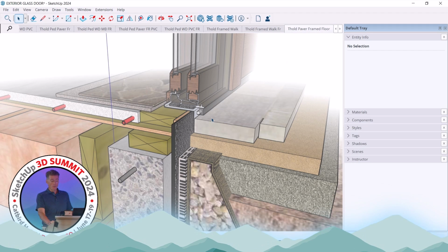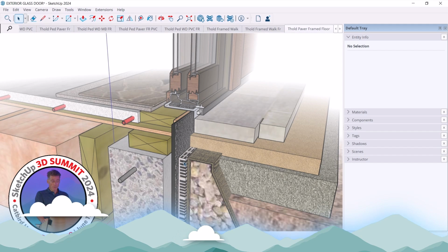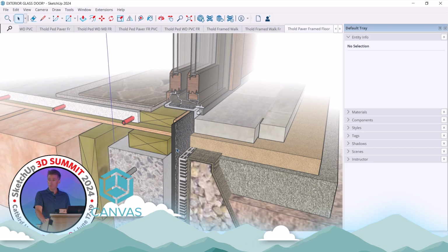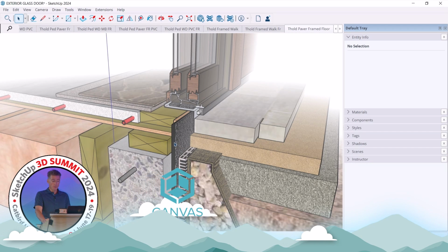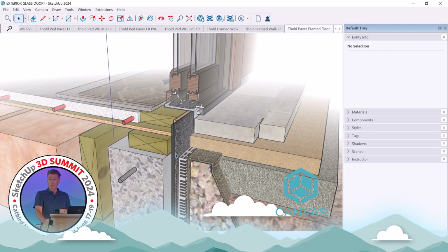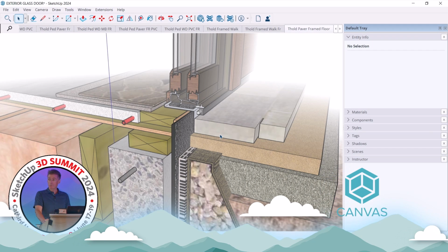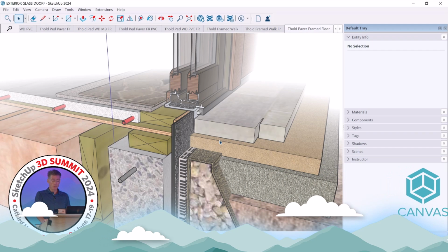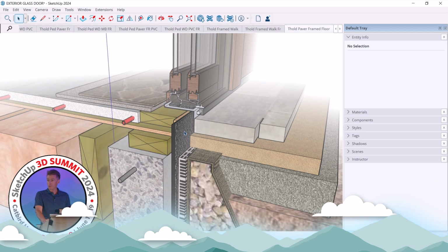And so this will continue down. This is a case where it's at a patio. And so this reflects the waterproofing systems that we use for all our crawl spaces, which is a multi-tiered system. So we will have a mirror drain system, to a sheet waterproofing, to a sprayed-on waterproofing system. We've run into too many leaks in our area that it's better to be safe than sorry, especially with these lesser expensive materials to add them up.